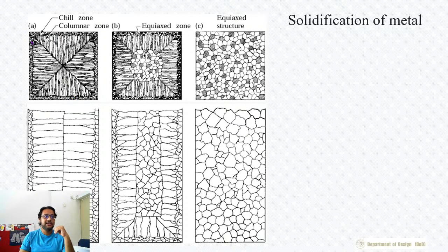Here the outer layer, as you can see, has smaller grain structure, because that area was able to lose a lot of heat very fast to the environment. So you have smaller grain structures, and as you go inside, this layer itself becomes like an insulation layer for the molten material that is now remaining on the inside of this block. As you can see, smaller grain structures all around.